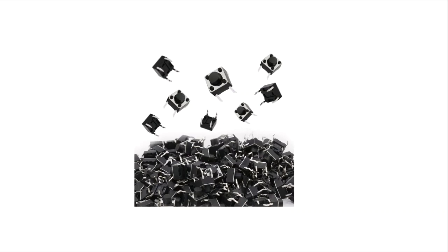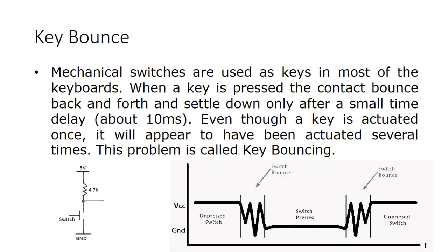a major issue of contact going back and forth due to the spring pressure. So when you connect a switch and push it, there are chances that it can give a false reading. When you press it, here it should read a 0, but it is possible it can read this 0, and this 0. So there are chances that multiple zeros will be read. This settling time can be as large as some 10 milliseconds. So you have to take care of this